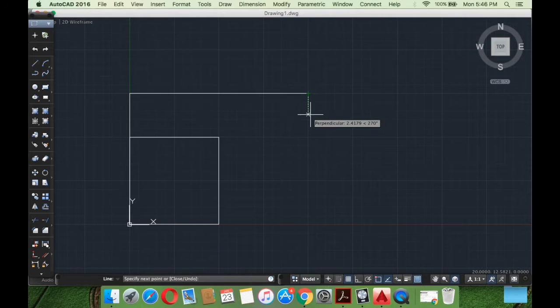And then we come down with the measurement. So we need to come down 15 boxes. So y-axis becomes 0 and x-axis maintains its position, so 20, 0. And we come back to the initial position, 0, 0, and we come out of the command. As you can see, we have created a rectangle with the help of coordinate systems.